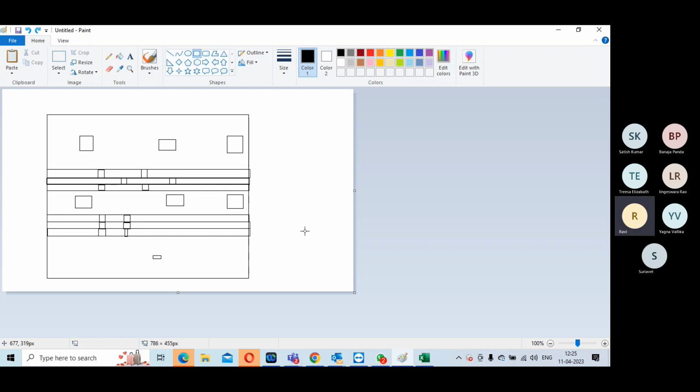So in a shut-off domain, what are the special cells that you are going to use? Isolation, you are going to use. Tie high, tie low, you will use in all kinds of domain. What are the special cells that you are going to use in a shut-off domain?